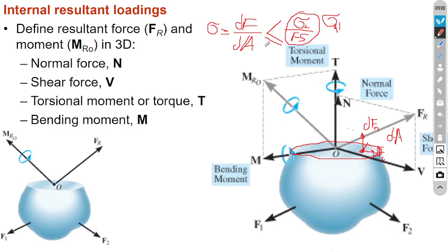The unknown may be the diameter of a shaft, thickness of a slab, etc. We derive the governing design equations using the stress definitions. Stress must be less than the allowable stress. Writing such design equations, we commonly use engineering stress.